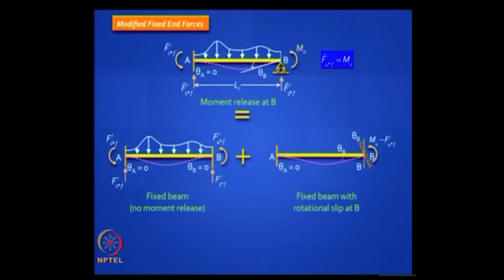So you allow it to rotate and then you will get some reactions at the other ends. What will be those reactions? Well, there will be a carryover moment, remember, we have done this before. Let me explain once more. Here you have to reverse this moment, then only you will get 0 from the loading, but in case you have a constant moment here, you better apply that as well, right. If you apply this here, half of it will get transferred here, and the shears can be easily calculated by the sum of those two moments divided by the span.